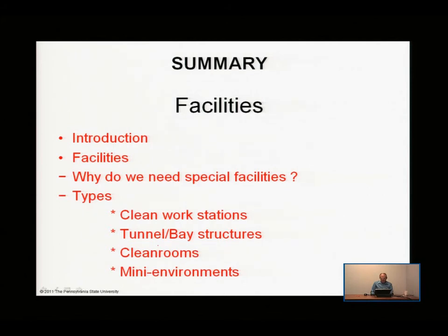We talked about class 1, class 10, class 100, and so forth, and how that's maintained with, again, flow through HEPA filters and constant exchange, up to 6 times a second in class 1 clean rooms.